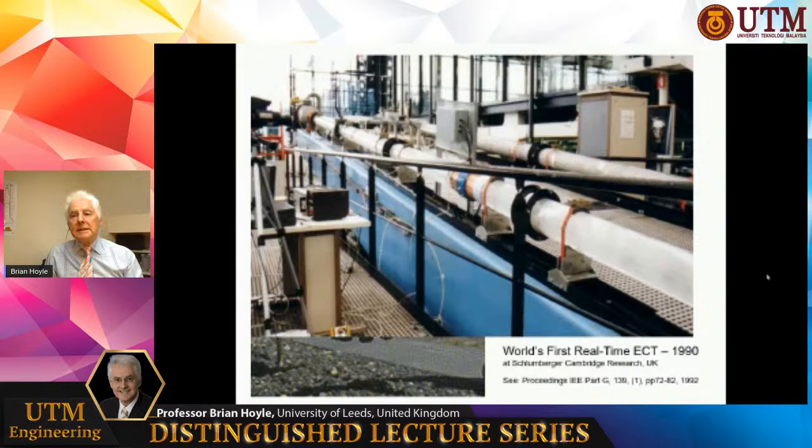ECT system. We did this work in conjunction with a company called Schlumberger, who are an oilfield services company based all around the world, and they have a large research laboratory in Cambridge in the UK. And in 1990, we used this flow loop, which is a 50-meter loop, which is inclinable from the vertical to the horizontal. So the vertical down to the horizontal. As you can see, it's slightly inclined here. And here's the sensor. You perhaps recognize it. It's got some electrostatic shielding, and I think it's a 12 electrode system, this.